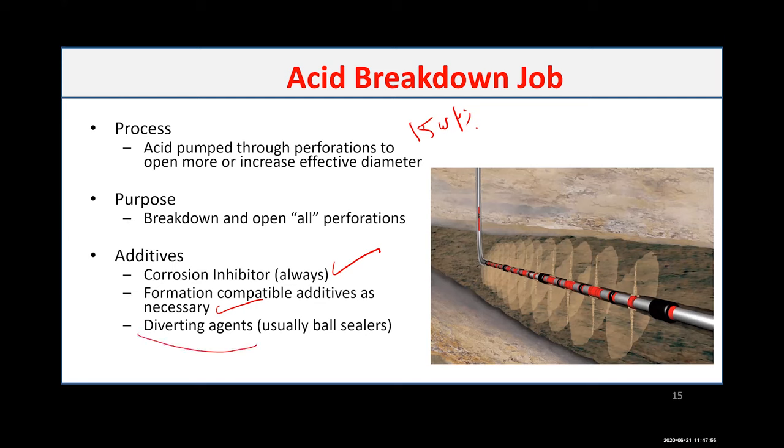As you can see, in this case I have a horizontal well with multi-stage acidizing. So after you inject in a certain perforation, you need to plug this perforation and allow the acid to go to another one. And we'll talk about acid placement at a later point.